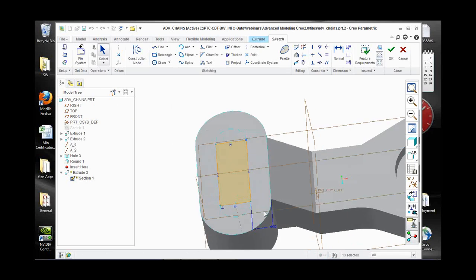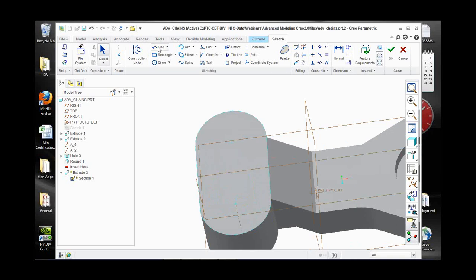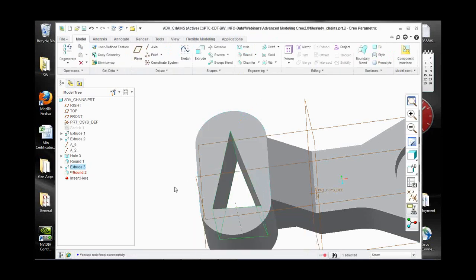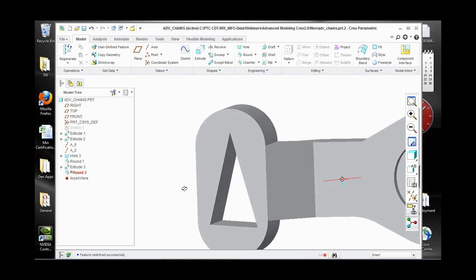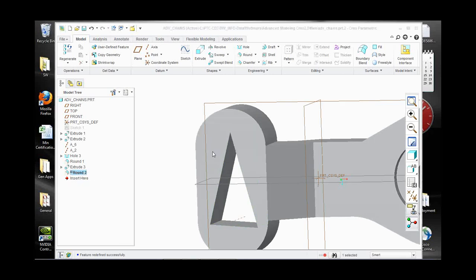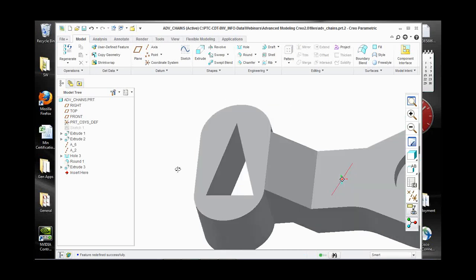Now most users know this: if I come over here and delete this, and then put in a new shape, whatever that shape may be, when I go and finish this feature, let me drag this out of the way so I can see that, my round is going to fail. Everybody should know that, being an experienced CAD user. But if you haven't done this before, instead of using edges themselves, we use something called intent edges.